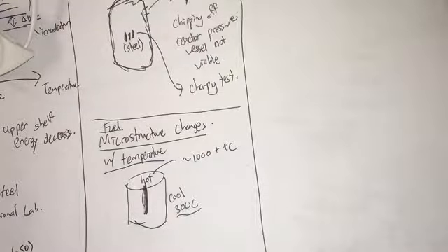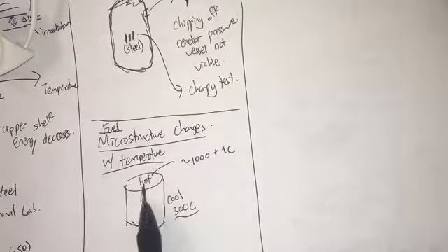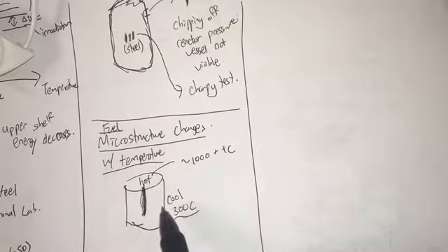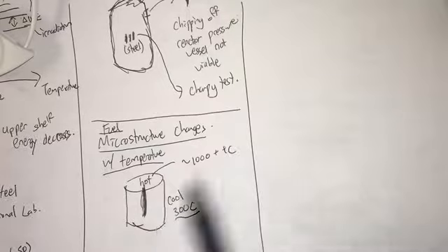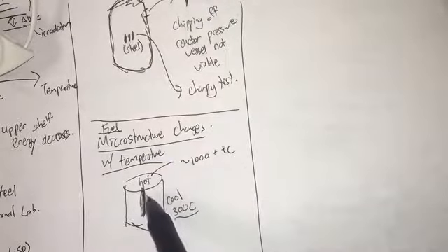And we're also saying that we are concerned with the thermal conductivity of the fuel because we don't want the central portion to be so hot that it starts to melt. And sometimes melting does occur, and we can see extensive recrystallization of the fuel in the center of the pellet.